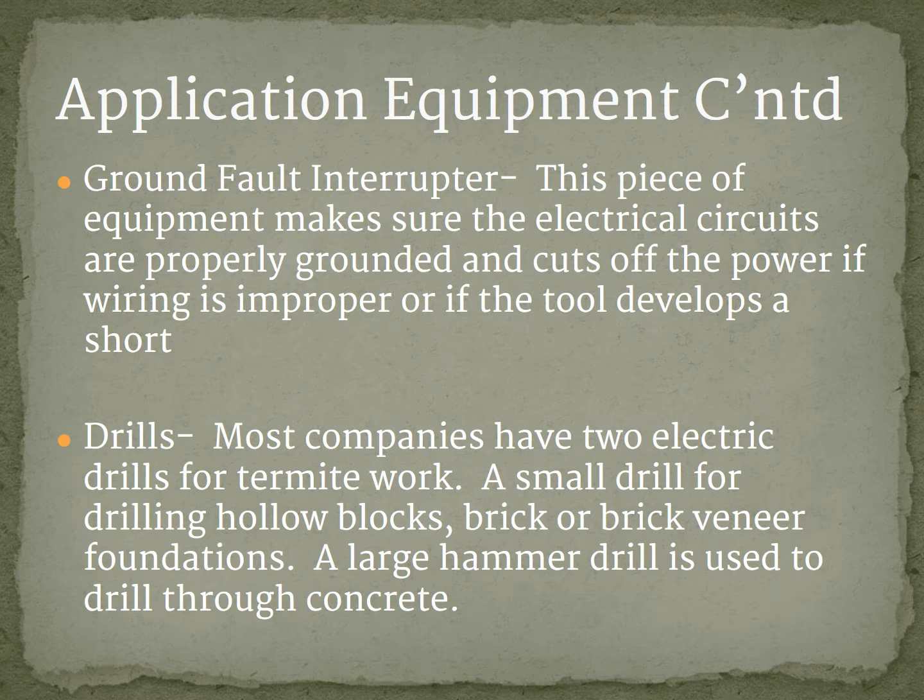Looking further at application equipment, there is something called a ground fault interrupter, and it's a piece of equipment that makes sure electrical circuits are properly grounded and cuts the power off if the wiring is improper or if the tool develops a short. The reason why you use this is you don't want to get electrocuted.